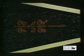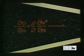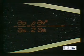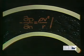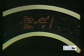Likewise, in steady, non-uniform flow, a tangential pressure decrease will accompany an increase in velocity along each streamline, and a normal pressure decrease will accompany streamline curvature in that direction. We shall discuss a few cases of unsteady motion at a later time.